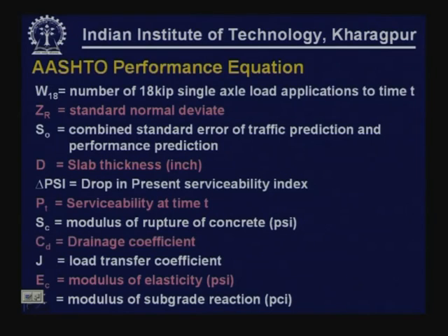PT is the serviceability at time t. SC is the modulus of rupture of concrete, flexural strength of concrete. CD is the drainage coefficient, which reflects the drainage conditions that would be prevailing. J is the load transfer coefficient. EC is the modulus of elasticity of concrete, and K is the modulus of subgrade reaction expressed in terms of